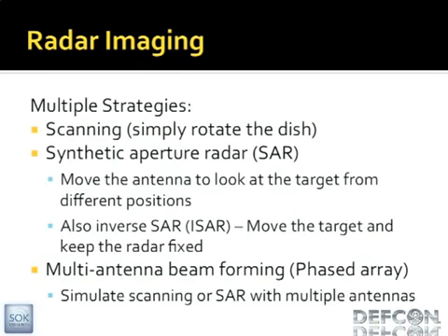There's something called synthetic aperture radar, which basically means you can get better resolution if you have a bigger dish. But the problem is that bigger dishes are more directional, so that's the advantage. With synthetic aperture radar, you're taking coherent measurements of the signal at different places, and you're trying to simulate having a larger dish. The reason you would do that is to get a finer resolution of space. If you just point it in one direction, the beam widths on these things are like 40 degrees or something, so you couldn't see anything out there. But the idea is that you make it highly directional by simulating measurements from multiple places, and then you can combine all those measurements together and get a cross-range plot. I can't do that live right now, but I will show you some pictures of that.